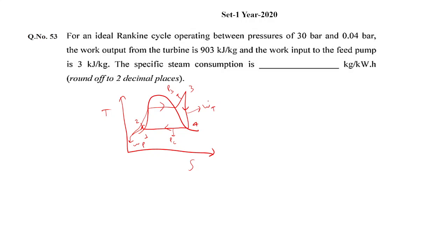What is the aim of the turbine? To achieve expansion of the fluid and get the work, and here we increase the pressure of the liquid by the pump by giving work. So what would be the net work done? WT minus WP, which means whatever we get from the turbine minus whatever we give to the pump. Because in the power plant, I haven't taught this, so I told it. Now anyone can start and let me know the answer. Now I have given the hint.